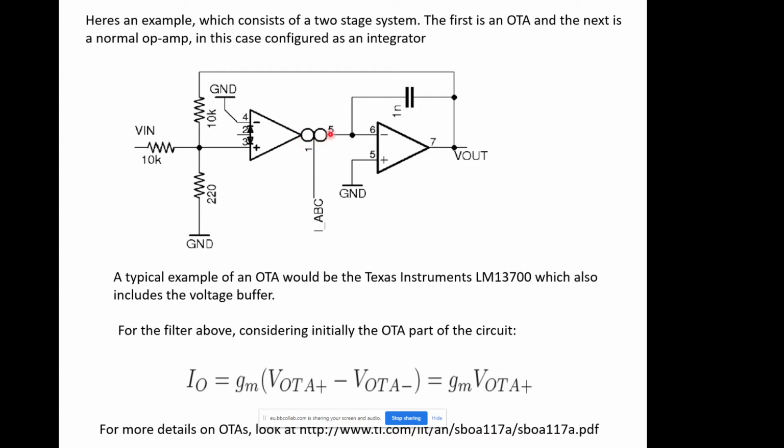So it's an integrated form of the sort of thing we looked at just now. In this case, if you want a frequency response, you follow that by a current to voltage converter, but with an integrated stage in there as well, because we want to introduce a capacitance for a filter. If you didn't want the filter response, you just wanted an amplifier, you just change this capacitor for a resistor to make a transconductance amplifier to turn the current back into a voltage. So this is just another way of changing the gain of this system. You just change the current going in here.